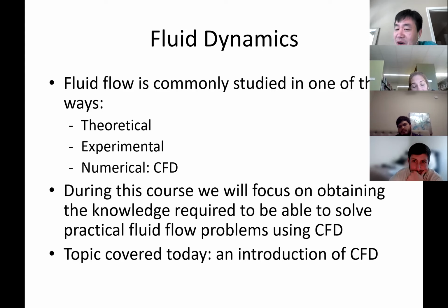When you do an experiment, for most applications you have to use the same size. A scaled model doesn't tell you anything. Well, basically, it's garbage. The experiment for the scale model, for some applications it's okay, but in many applications it's not, especially when the viscous effect is dominant.